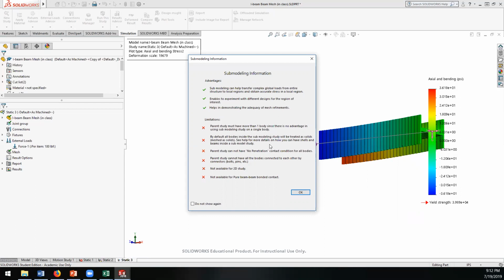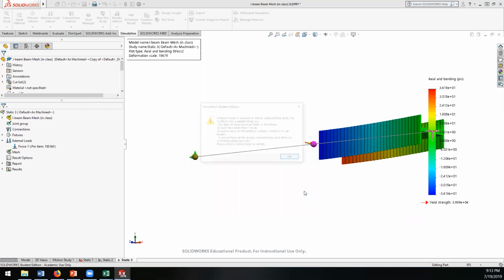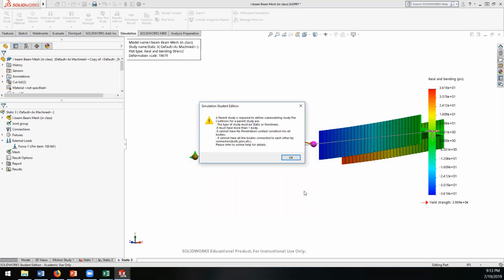So they're all meshed as solids. I guess there's some help. You can change it. Anyway, so there's things where you can have the suspension and frame together. Or a good example might be the kingpin with the A-arm. Maybe you guys get the forces at that kingpin, and then you attach the A-arm.